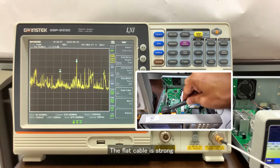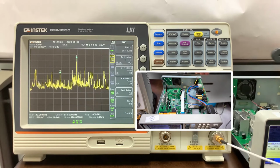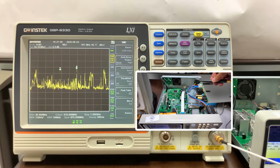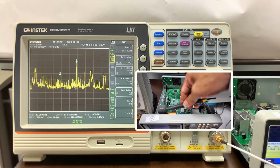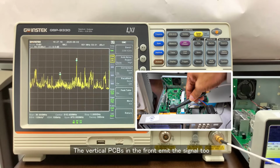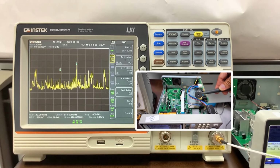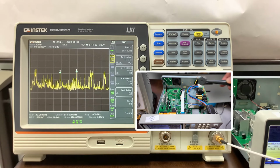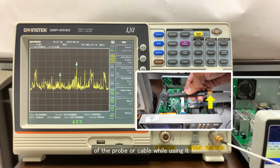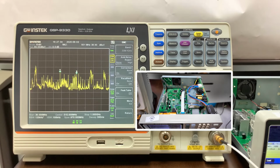The flat cable is strong because it's just like an antenna to radiate the signals. The power section is not so strong. The vertical PC board in the front emits the signal too. Here we need to be careful that do not touch the metal ground of the probe or cable while using it, so those unnecessary signals won't be detected through our body.